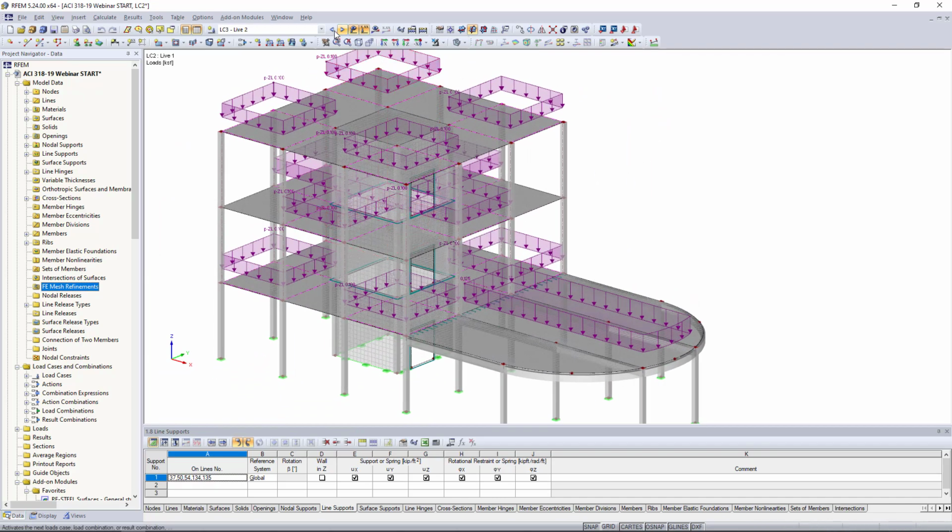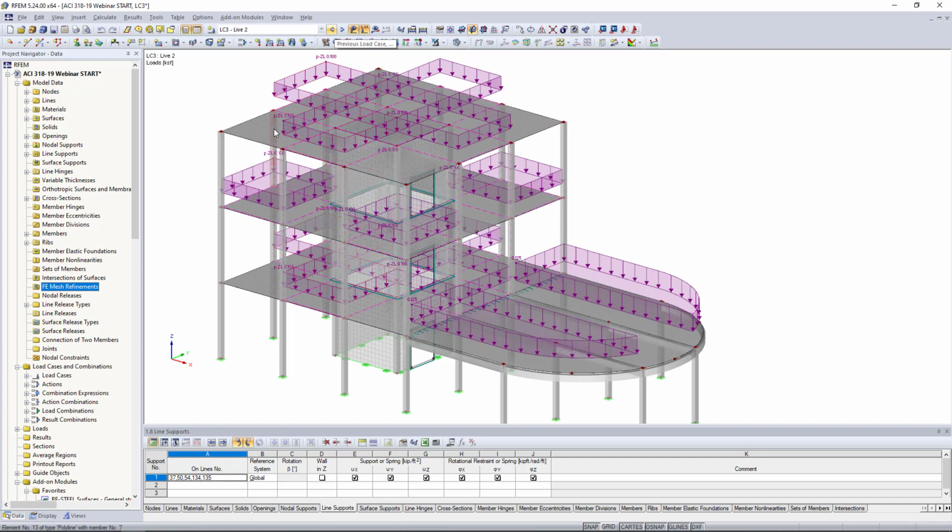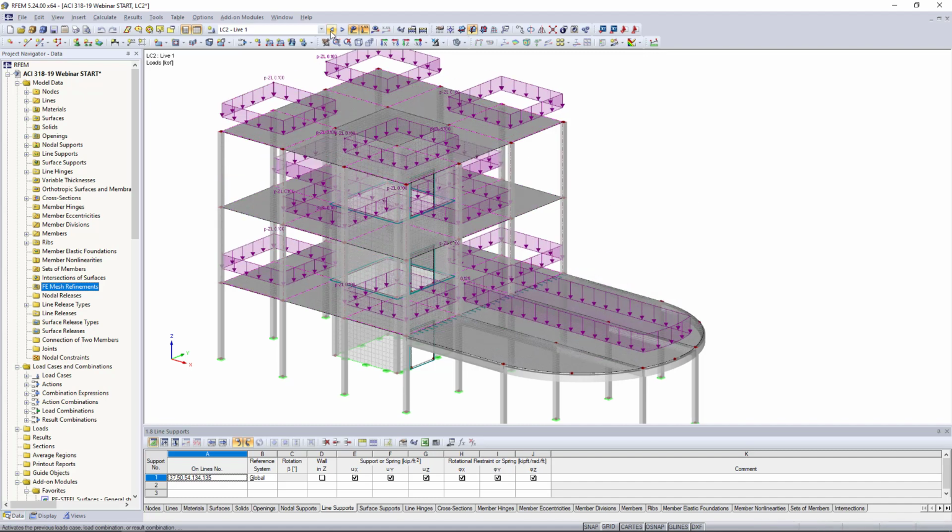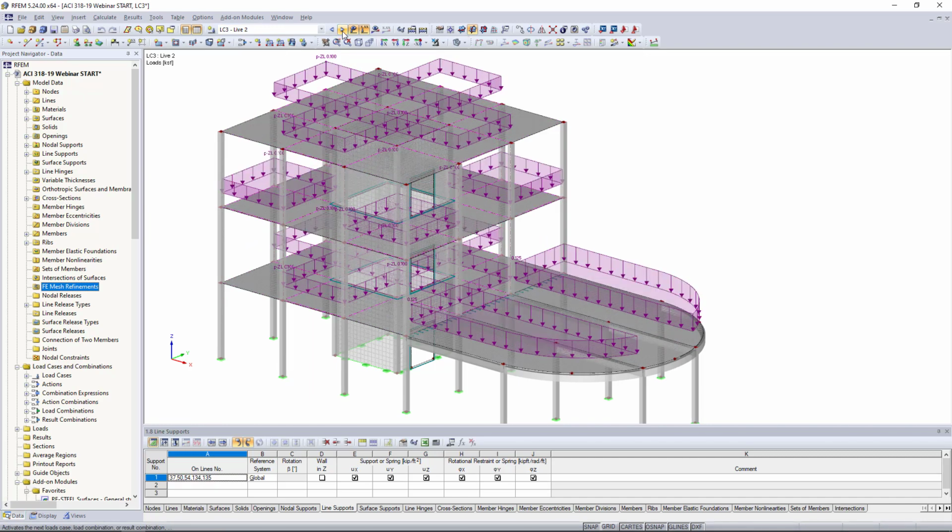We take a look at our second live load case, we have some different arrangement here. So this might be live load considerations that we wouldn't want to consider together, but it's one or the other. So I've set up my load combination so that it's not considering both live loads together, but rather the load combinations will consider live load 1 here or live load 2.